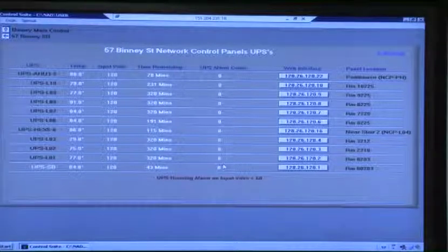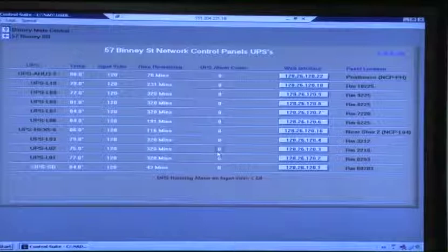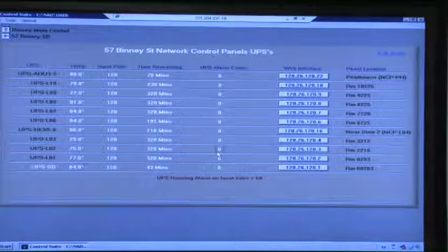So now you've got to take action because it's on UPS. You can look at it and say, hey, I've got 43 minutes left. After 43 minutes, I know I'm not going to have power to my controls. Over in the CLS building, we've had UPSs drop out, and we've had to go over and plug into normal power. Exactly. So this is going to tell us we need to go over there, get into another outlet that serves it, to keep our systems up.